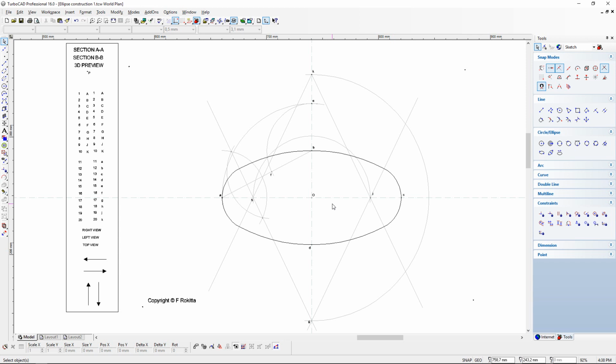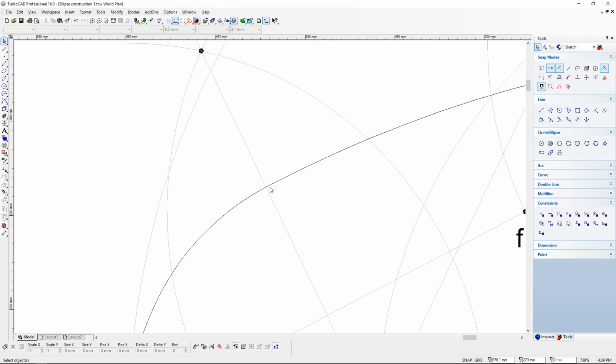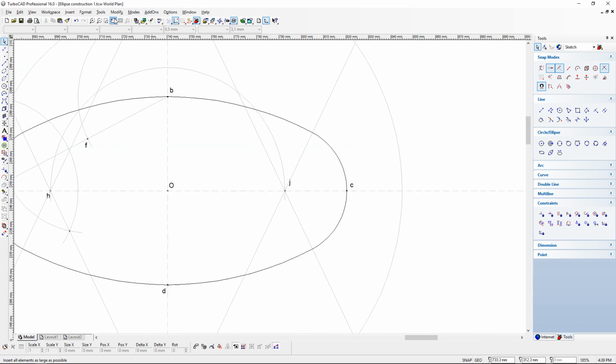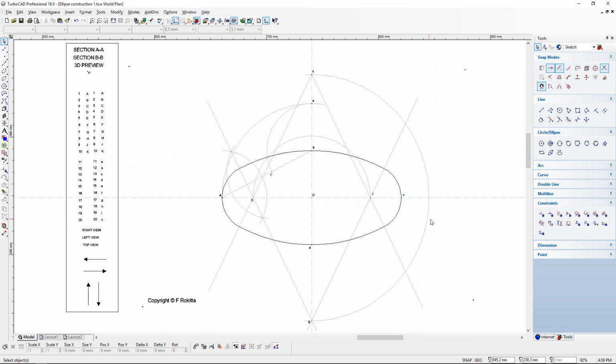Now, like I've said before, on paper it might be that your lines do not meet accurately, especially by the meeting point at the diagonal line at the top and bottom. But practice makes perfect, and I encourage you to keep on trying till you get this right. My advice would be take a piece of paper, take your instruments, mount your paper to your board, draw your X and Y axis, determine the length of the X axis and the height of your Y axis, select your point 0 or O, and from there start with the construction step by step.